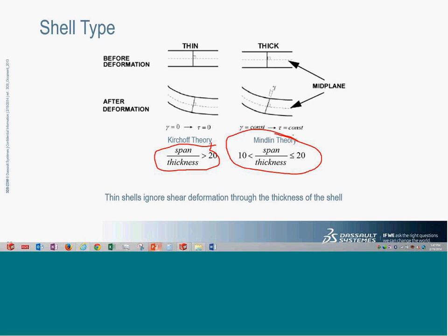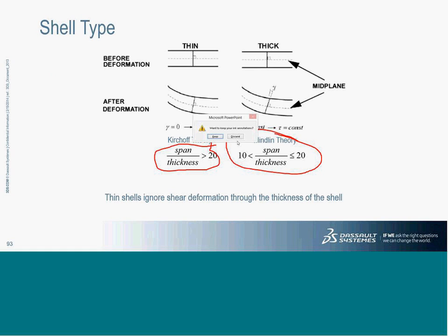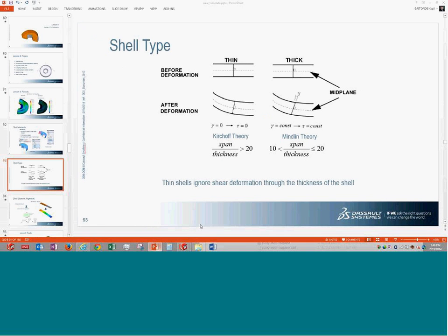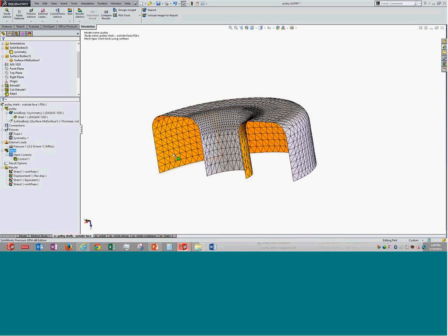Second, what I want to convey is what exactly the color means. It is not the color itself, but what we call the shell normal. When I check the surface over here, you see there is an arrow coming up. This is telling the normal direction of this shell. So in short, this is the bottom surface and the top surface is somewhere above that.